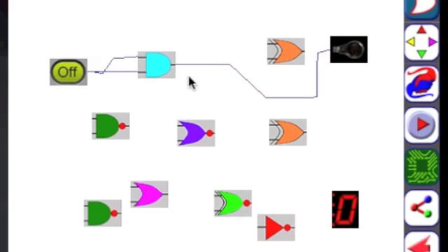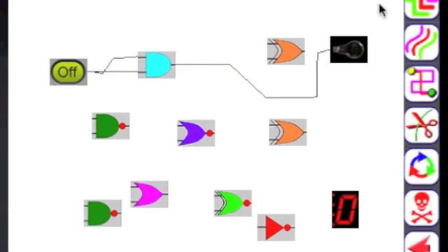Now once you create a circuit like this, you might want to update it. You might want to delete this wire and connect it somewhere else, or you want to change the way this wire looks like. Let's try that. That's what this icon does. So here are the options you have with the circuit. First one helps you select a leg to change the connection in a particular component. For example, this component is selected now. You can see it's blinking. Keep tapping this till the desired leg is selected.